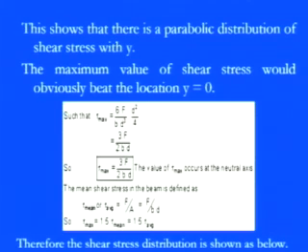So if you just go back, just remember those things. We were discussing the bending stresses, when a beam is under the application of bending moment. Due to the bending moment, the upper area of the beam is experiencing tensile stresses, and the lower portion of the beam is experiencing compressive stresses. But there is some locus of points where there is no stress component, and due to that there is no strain. But here, when the same beam is experiencing shear forces, the maximum shear stresses are at the neutral axis only.